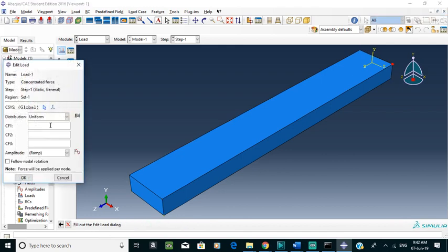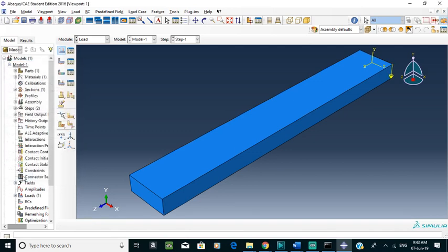And these are directions of loads. So for that direction, it will be 0. In this direction, the positive value that you're going to put is actually going to give you an upward force, but I want a downward force, so I'm going to put a negative sign right there. So I'll make this 45,000, then in that direction it's 0. So right there you have that arrow pointing downward as your downward applied force, 45,000 Newton.